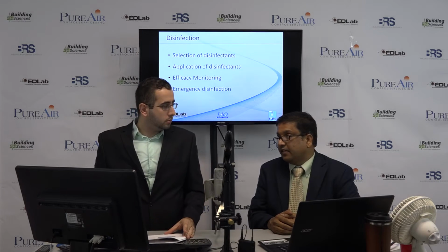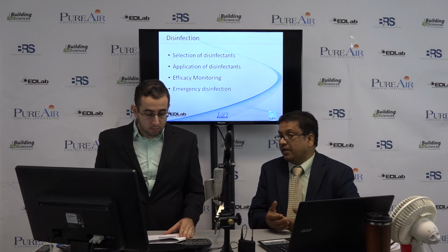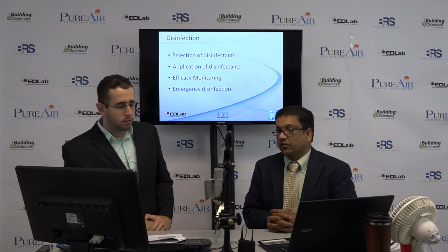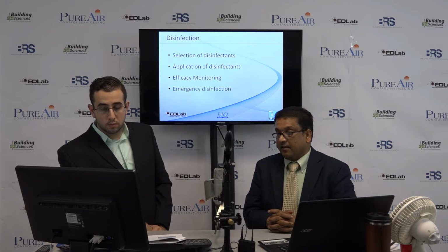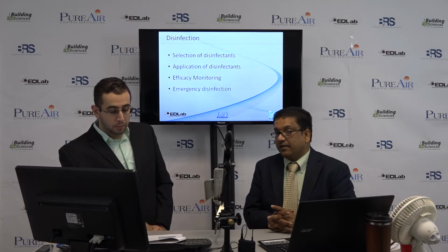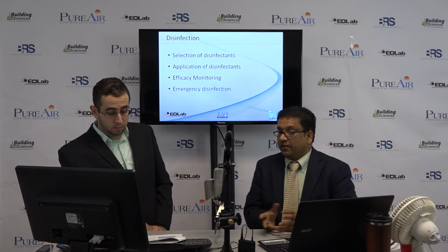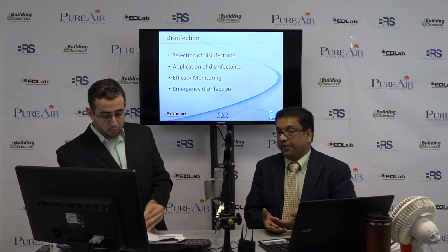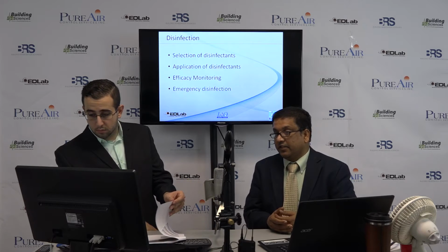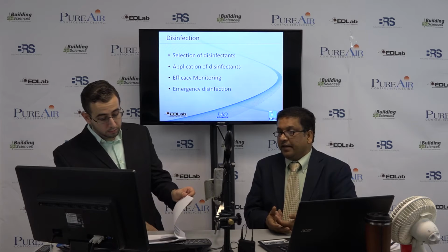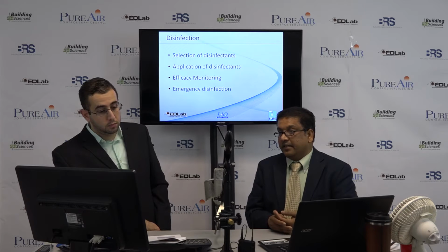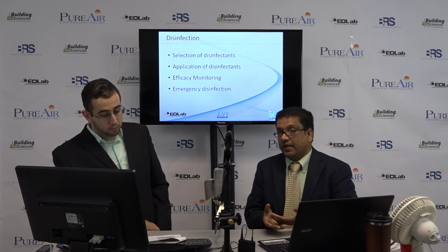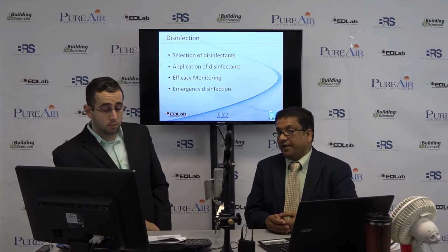So selection of the disinfectants is the main thing, because once you know what kind of method one should take, it gets disinfected. Nowadays everybody is going after green technology, and I support that, because there are several methods by which you can disinfect. The first method is that people use chemicals such as chlorine to disinfect. Then there is a heat method. In the heat shock method, you raise the temperature for a certain number of hours, and the bacteria don't survive at those temperatures, so the bacteria are killed.